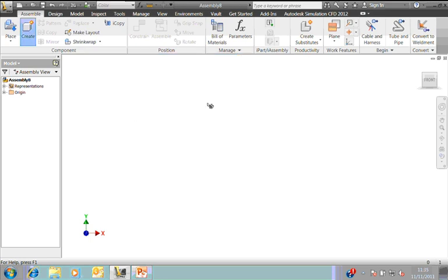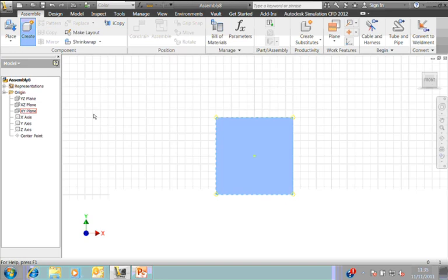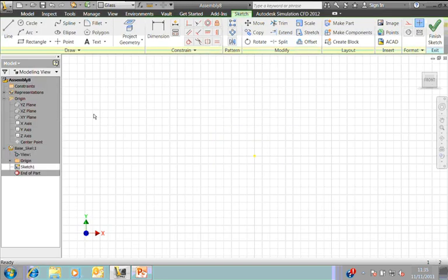The other thing that you need to do when creating in-place components in assemblies is we used to say, well, just click on the screen to sketch on the XY plane. The problem we have these days is a lot of people have 3D connection manipulators, and it's good practice now really to select the XY plane from the browser instead to place your first sketch. You know then for sure that's on the XY plane. Otherwise you may have problems later on when you push this through to a 2D drawing, and we've had instances where the view is not quite flat on the drawing view.